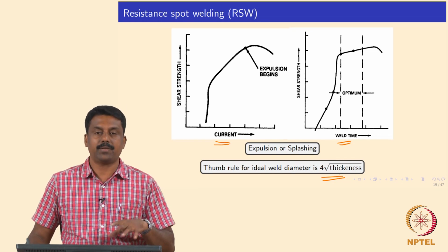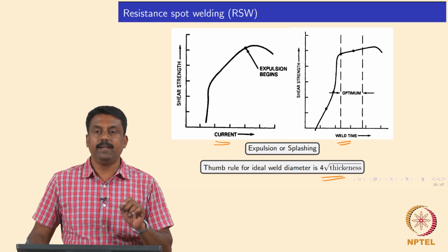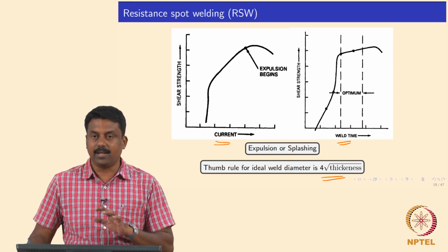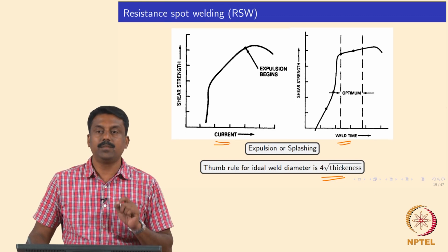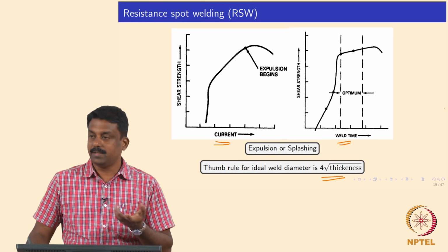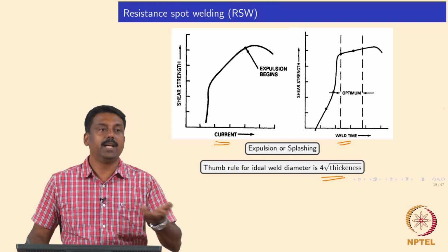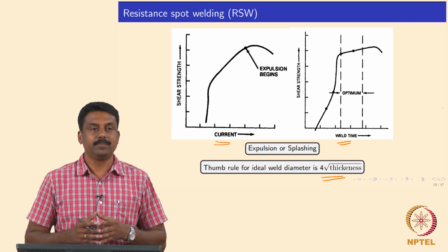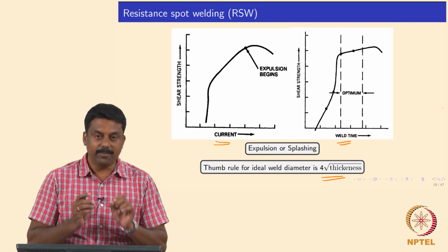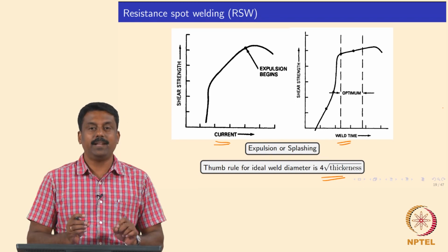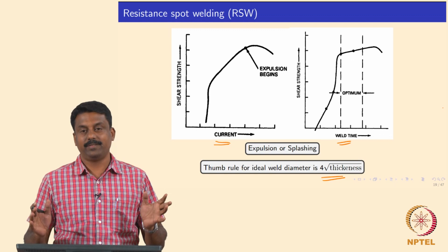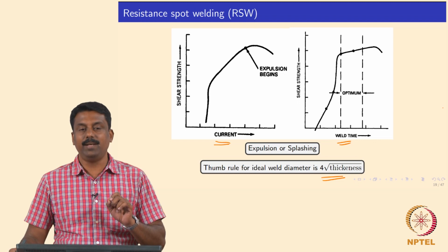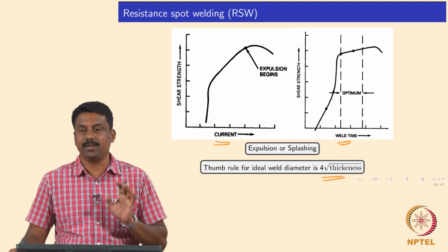That's what I explained in the introduction, okay. The weld growth curve is extremely significant to arrive at the required weld nugget diameter, and this is also influenced by the mass, the m, okay. In turn mass is influenced by thickness as well as the Cp, specific heat capacity. So if you change the chemistry slightly, if you change the thickness slightly, the weld growth curve changes, okay. So that makes this process extremely unstable for even a small change in processing conditions.